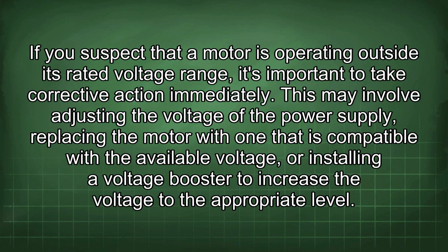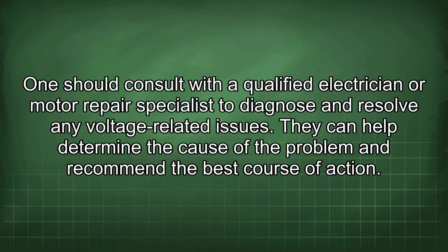This may involve adjusting the voltage of the power supply, replacing the motor with one that is compatible with the available voltage, or installing a voltage booster to increase the voltage to the appropriate level. One should consult with a qualified electrician or motor repair specialist to diagnose and resolve any voltage-related issues. They can help determine the cause of the problem and recommend the best course of action.